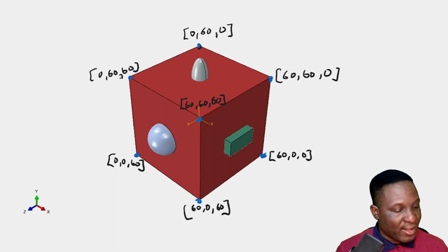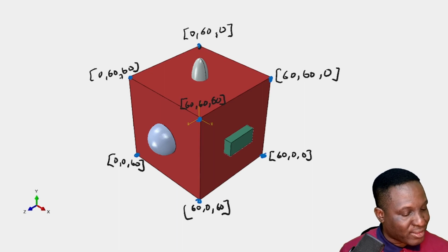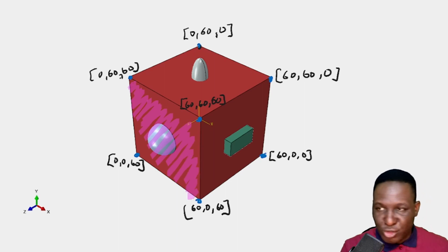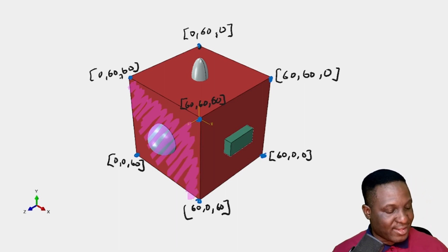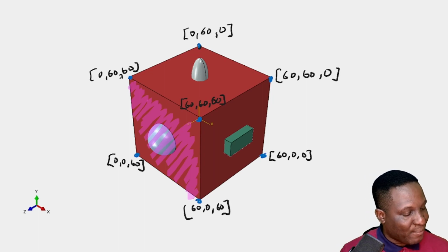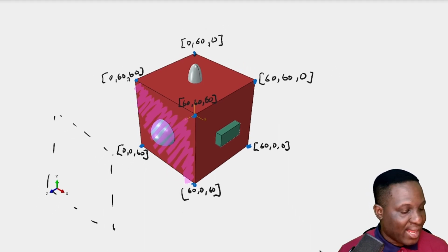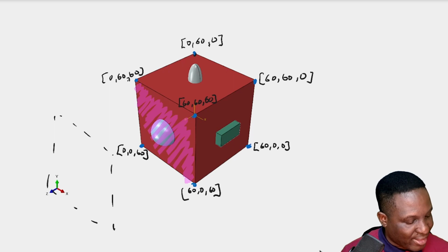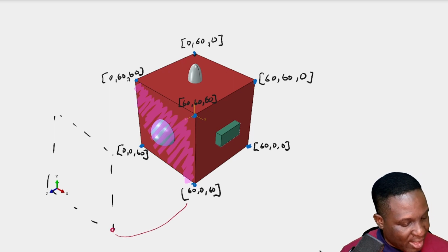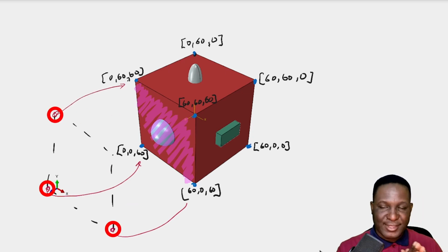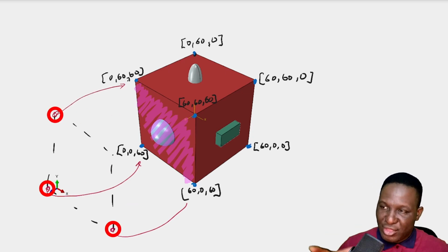Remember, the first case is the one we're going to focus on only, because with that system we can then extrude cut so that we can cut through with the block case. What we need to do with this first instance is create a datum plane, and we need 3 points to create it. So we use this point that is linked to there, and this point that is linked to there, and that point that is linked to that. That gives us a datum plane created based on 3 coordinate points.